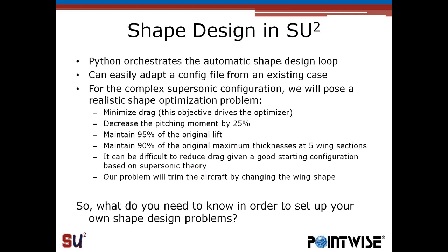After that, Python is going to go ahead and take over. It's going to call our C++ modules, compute the flow and the adjoint, deform the surface and the volume mesh, and run the whole design loop for you. And one of the key ideas here is you can usually adapt an existing config file from an existing case to your needs.